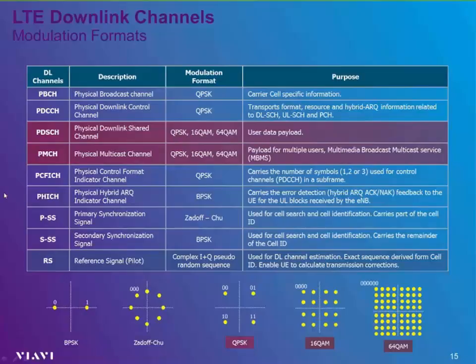But at the top here, notice there are a variety of different modulation formats. Again, LTE is intended to be a preemptive technology, meaning from that reference signal, it's going to tell the base station through CQI values what the RF conditions look like. If the RF conditions are really poor, the base station is going to send out the data using QPSK modulation, because 4 points of modulation is far more robust than 16 or 64 QAM. If RF conditions are ideal, it would like to use 64 QAM. And again, through the CQI values reported, this otherwise determines, as far as your vantage point, what type of throughput you can gain or receive.